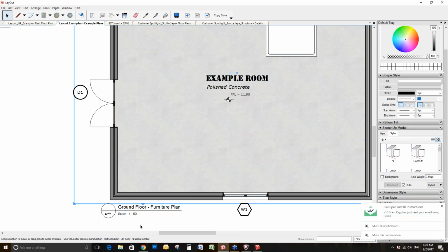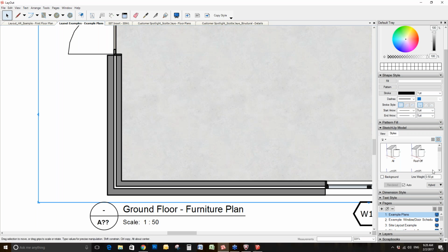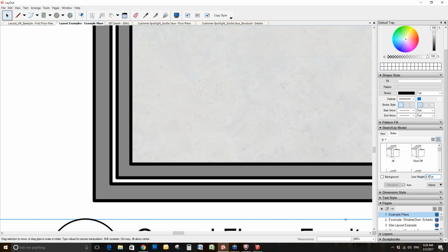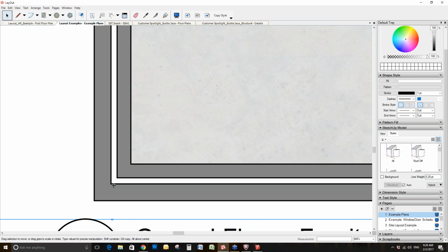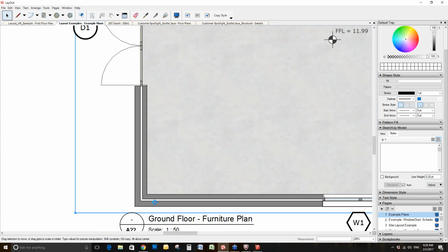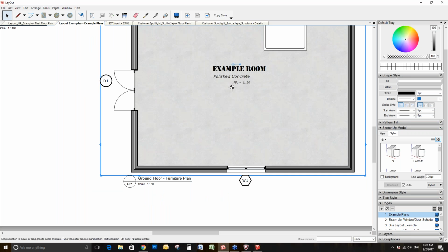So at this particular scale, I could decide that the line weight is not reading as heavy as I want it to, so I can actually add to it. So I might go to a 0.7, for example. And once that updates, you're going to see that it's going to go a lot thicker. I actually did 5.7 there. Let's do an actual 0.7. There we go. And if I go lighter, still a 0.2, you can see that it's going to lighten your overall drawing. So you've got an overall control of your sections and your overall line weight thicknesses in your model.